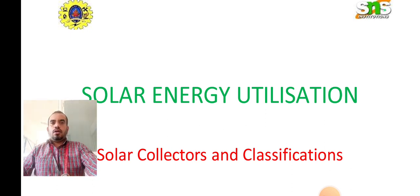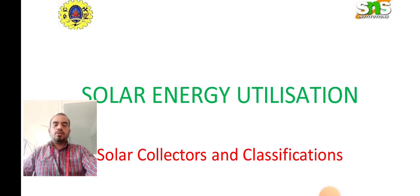We are going to see the solar collectors, and later we are going to see the classification of the solar collectors. First, a solar collector is a device designed to absorb incident solar radiation and to transfer the energy to a fluid passing in contact with it. Normally it collects the radiation of the sun and transfers that radiation to the fluid which is passing inside it.